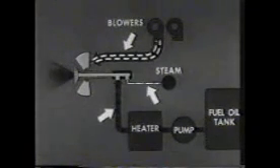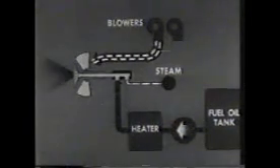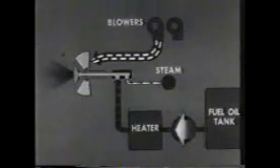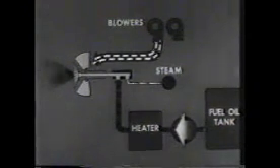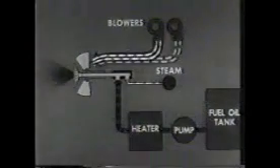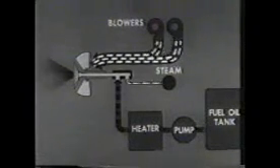Meantime, the air from the forced draft blowers is entering the register and mixing with the oil spray. Control of the burner involves regulating the air, oil, and steam supply. Regulate oil pressure to regulate the quantity of oil. When you increase or decrease oil pressure, you must change the steam pressure correspondingly to get good atomization. You must also change the sprayer plate in the burner if the capacity of the plate is incorrect for the new firing rate. As with most burners, you adjust the speed of the blowers and the number in service to control the air supply.